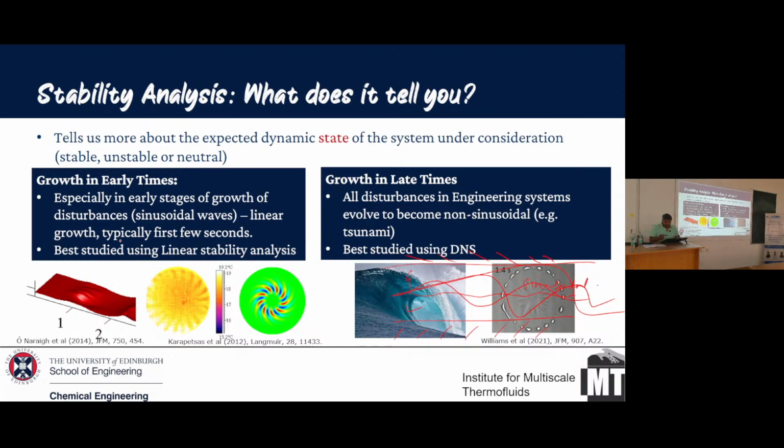Now, late times are pretty difficult to understand by linear stability analysis. Normally there's something called a nonlinear stability analysis, but we don't do that. It's quite unnecessary. So you have these waves which are developing into huge structures, and typically we study them using DNS.